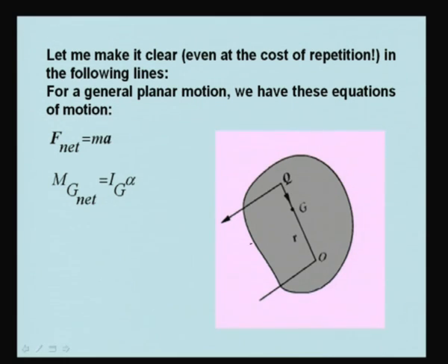Why? Because there was a force passing through G. I have shifted it in a parallel manner to another point Q on the same line. So now, if you take the moment about G, you will still get a moment, because the force is not passing through point G. So there is no need to show the moment. Therefore this has been shifted, and this point Q is called the center of percussion. Let me repeat these points because this is very important. So this point Q is the center of percussion we have described.